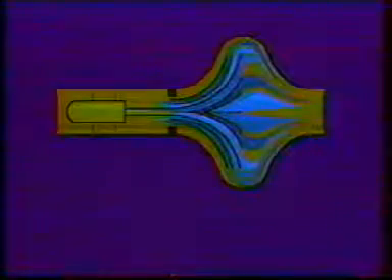A force sensing device measures the torque produced by the Coriolis acceleration. The amount of torque is directly proportional to the mass flow rate and can be used to calculate the flow rate directly. This device has a quick response time, so it is especially applicable for processes with rapidly changing flow rates.